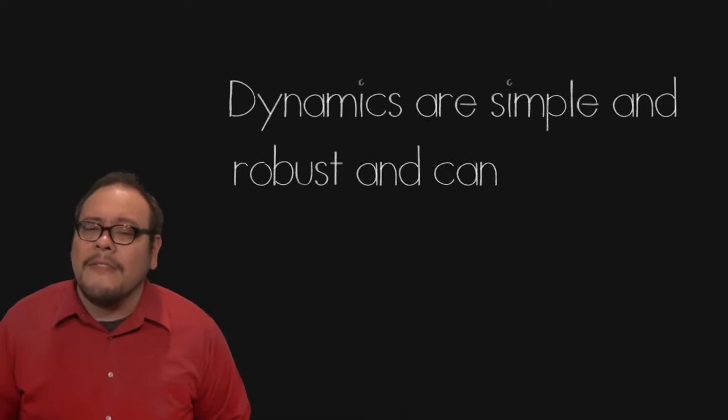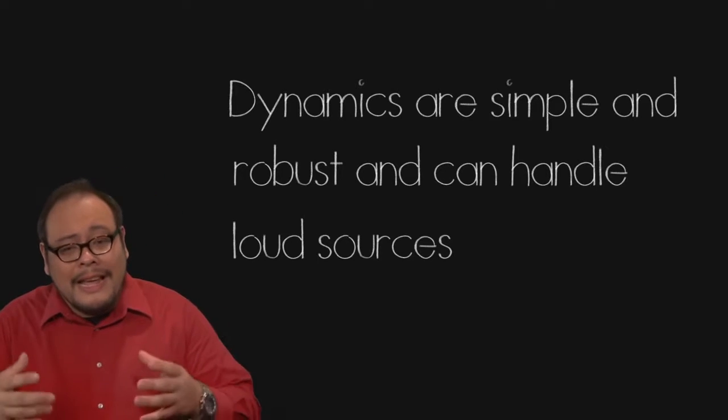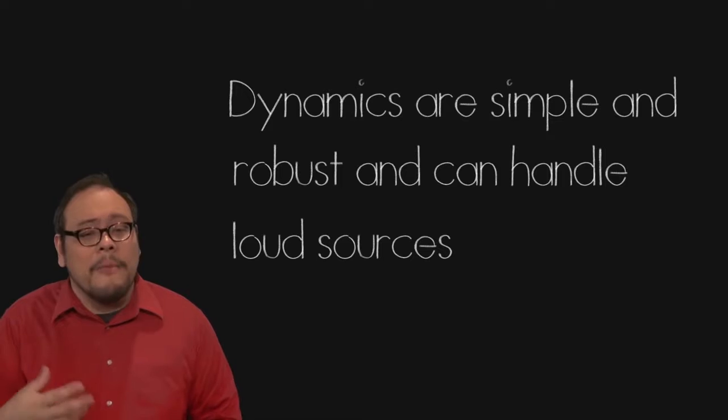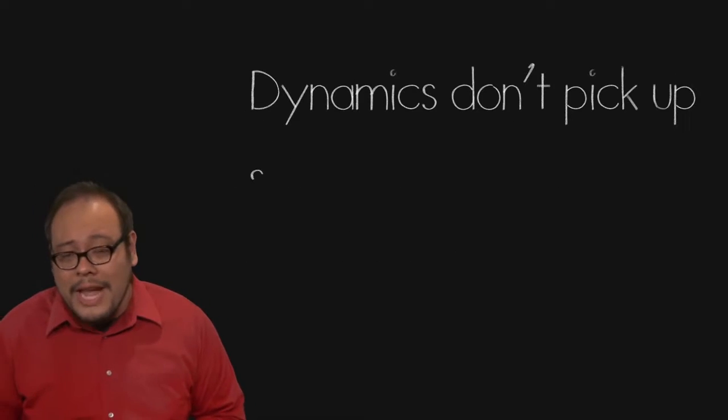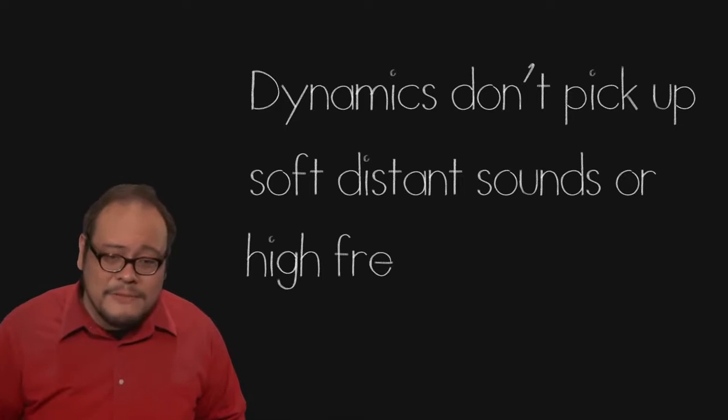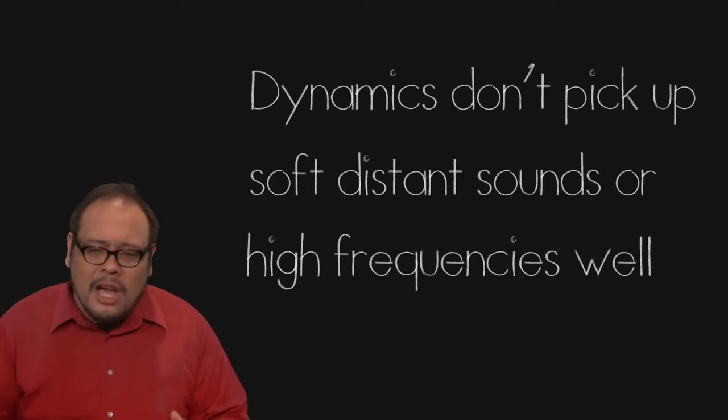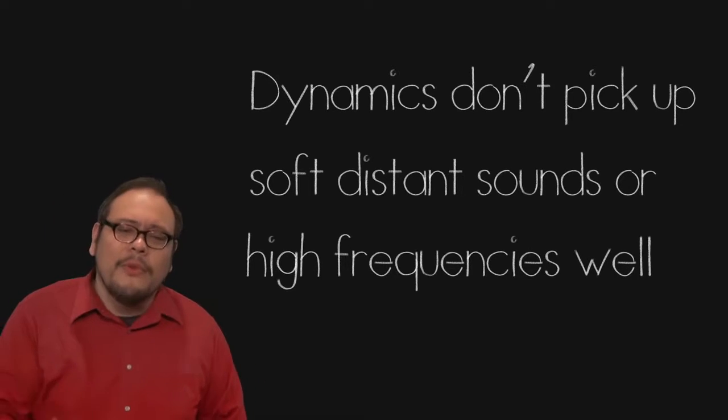Now, the advantage of the simple and robust design of the dynamic microphone is that it can handle loud sources without much distortion. Unfortunately, this makes them weak when trying to capture soft, distant sources because the diaphragm needs a lot of sound energy in order to move.